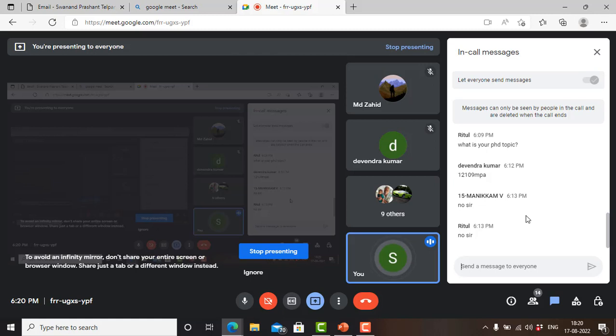Anyone got the answer? Root 3. Okay. 1.41. Okay. Anybody else? I will give you one more minute. We have to just find the surface energy of 100 plane and 110 plane in a BCC crystal, and we have to take the ratio of that.